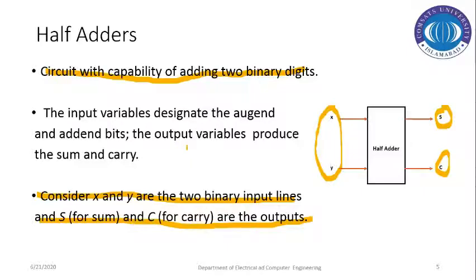So we have to design a circuit. We have to describe our design, which have the two respective inputs, that is x and y, and two respective outputs, that are s and c. And the name of the module should be the half adder.